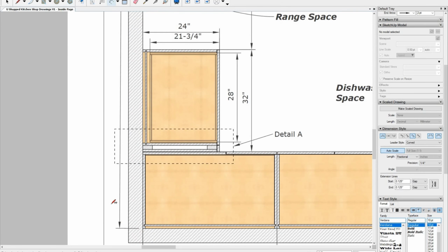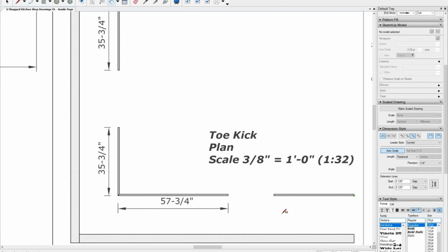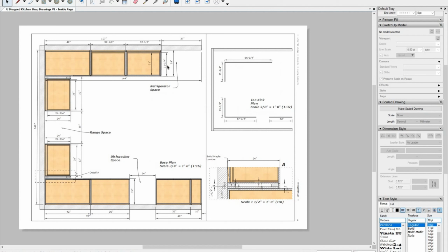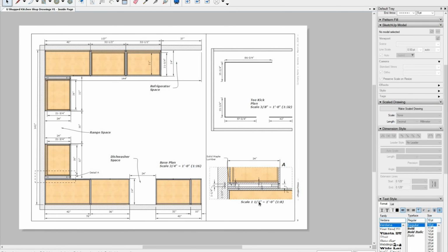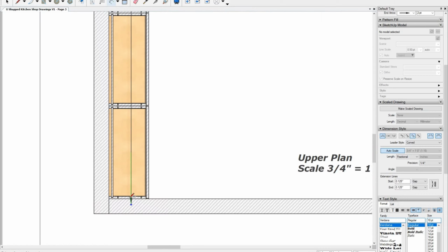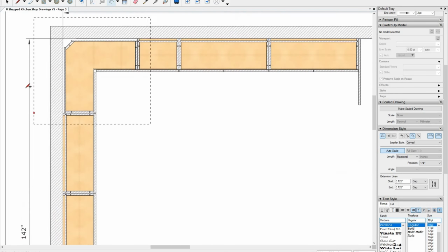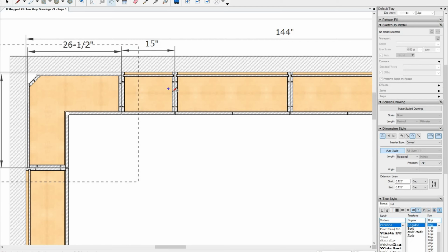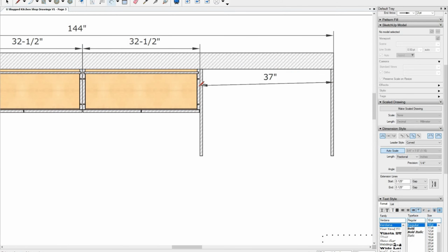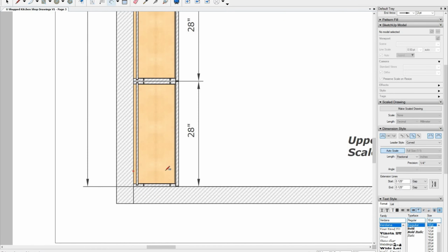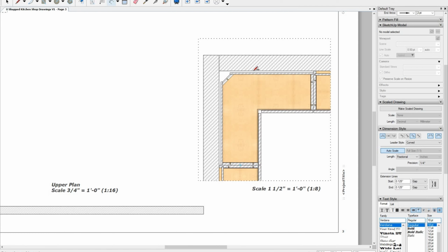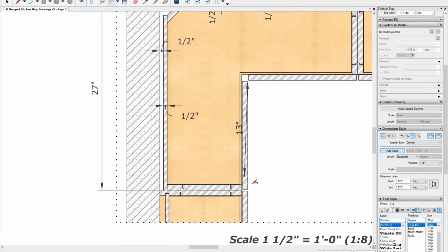it will not be automatically done on the layout unless it is something very small, but most of the time it affects many things. It also affects the cut list, so it is better to just nail it and finalize the details before you get into the shop drawings. Again, the shop drawings, I just make notes and I'll enlarge any positions that I believe the cabinet maker would like to know what assumptions or what design consideration I have done, so that they are going to follow, so that everything fits well.